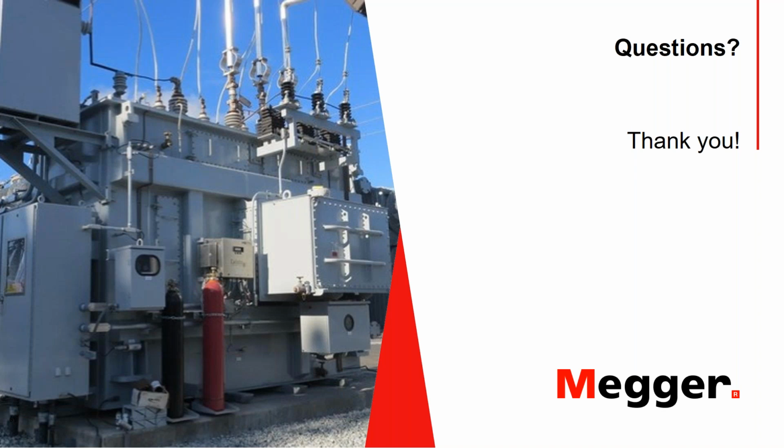That's an excellent question. Because of the nature of this presentation, we couldn't concentrate a lot on demagnetization because we had a lot of case studies. But demagnetization is a really important practice that needs to be performed after you complete winding resistance measurements. First, that's because you are saturating the transformer core with a direct current and direct voltage. That's not typically the normal state of a transformer when it's in operation.